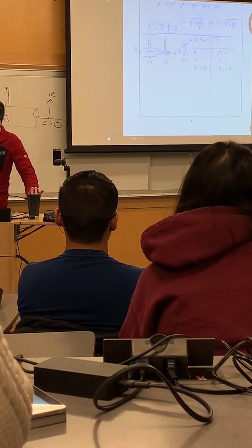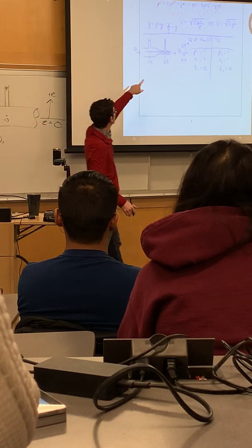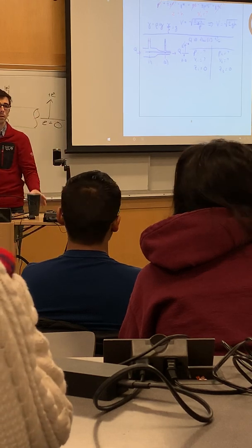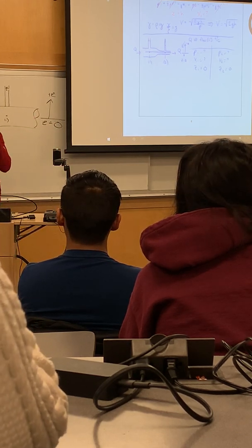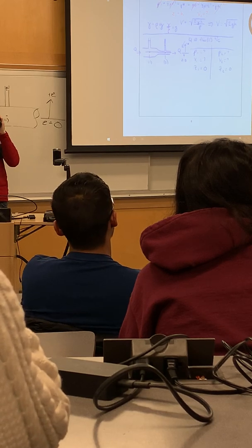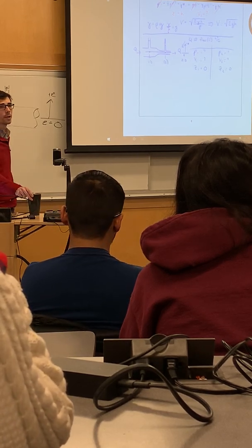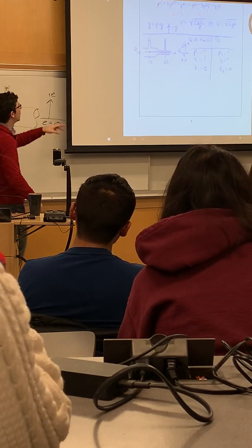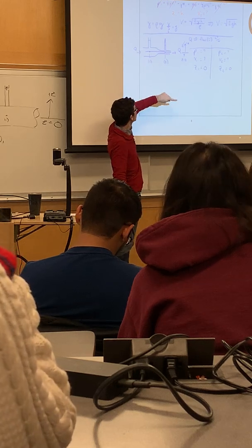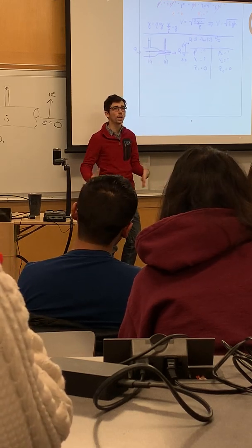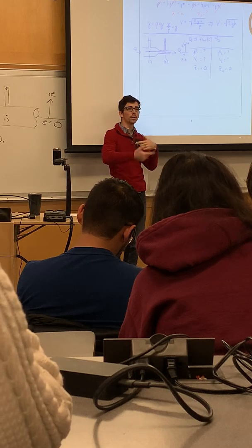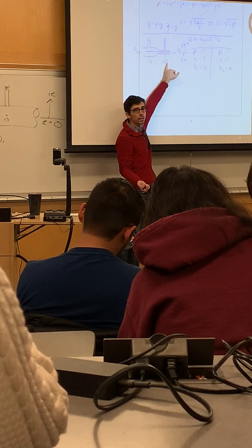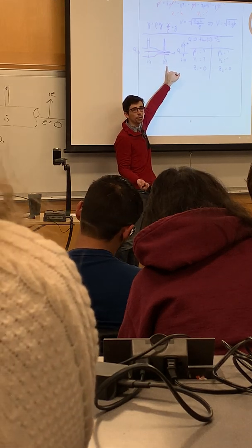P1 must be equal to P2, right? Well, it depends on the elevations of the manometers that are given. How do we define static pressure? Because in this case we have flow, right? So we're saying there could be some static pressure even though there is flow. Yeah, so essentially what's happening is that you'll see this, I think, as you start to work examples, you see how the Bernoulli equation accounts for the trade-off of static pressure at point 1 for velocity head at point 2, or dynamic pressure at point 2, right?